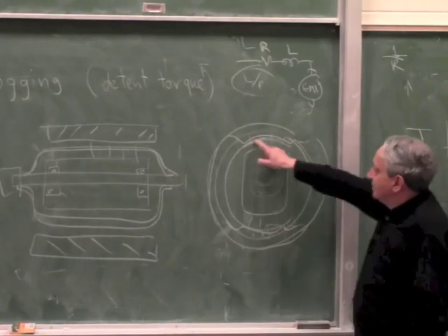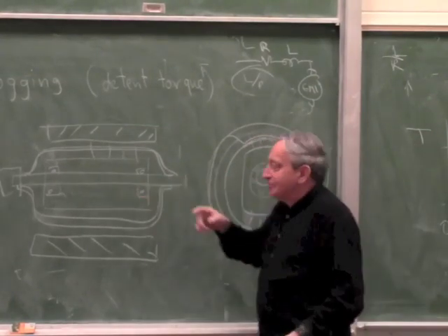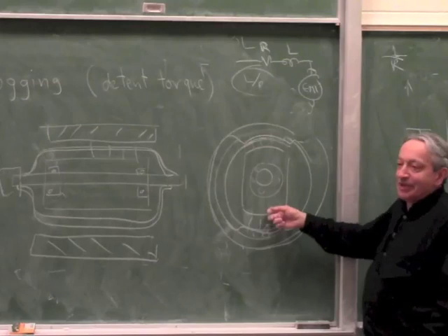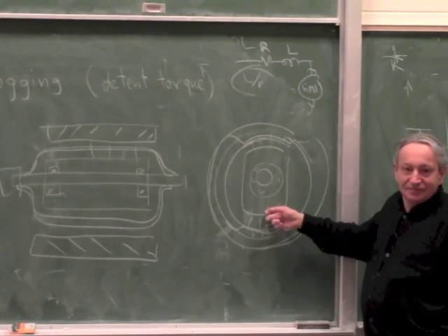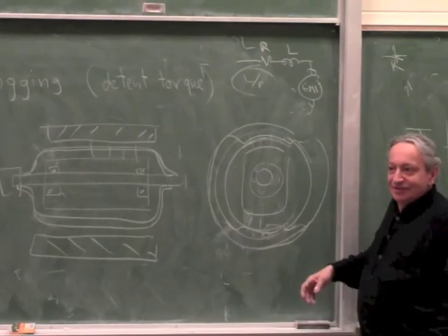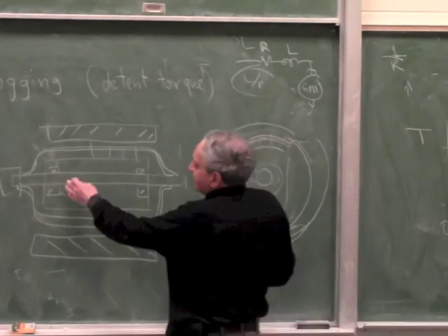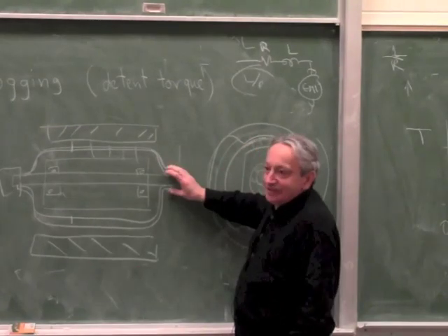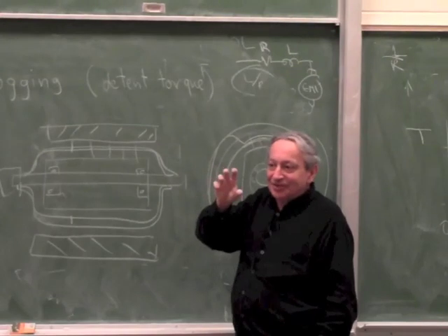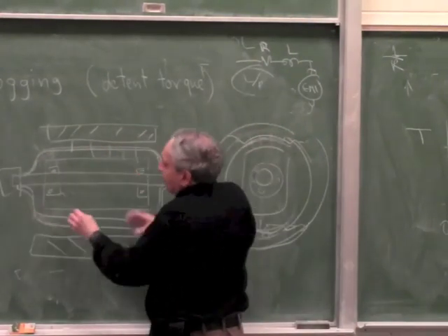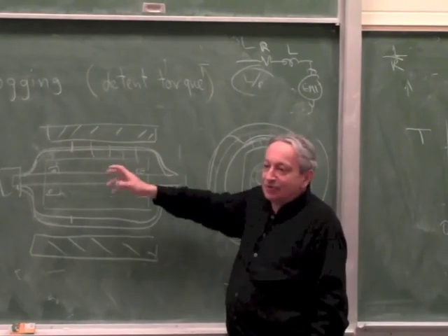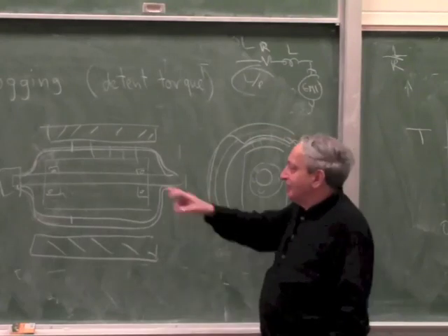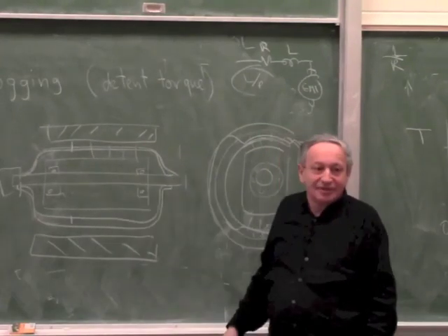Now when you accelerate it, this hollow winding accelerates, but the magnet, the shaft rotates, but the magnet stays in place. So you don't have to accelerate the mass of the magnet. Is that clear? Okay? Because in the normal motor today, it's the same as this, but it's cut off here. So the winding is only connected to one end. But you can only build it in small motors. But you can connect the winding in both ends and have a free-floating magnet inside, or a free-floating iron core. And the magnet can be outside. Okay? So the only inertia you have is the inertia of the winding. You don't have to have the inertia of the magnet.